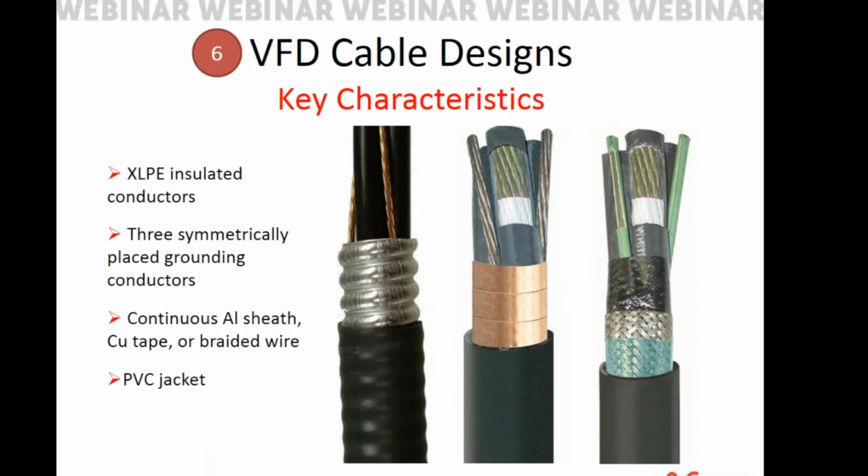Well, cross-linked polyethylene nowadays especially is of such a high quality that it can maintain its integrity with these repetitive spikes of 2 to 3 times its voltage rating. So really our 1 kV VFD cable can work with these voltage spikes if they go into the 2 to 3 kV range. So 1.9 kV repetitive spikes, no problem.